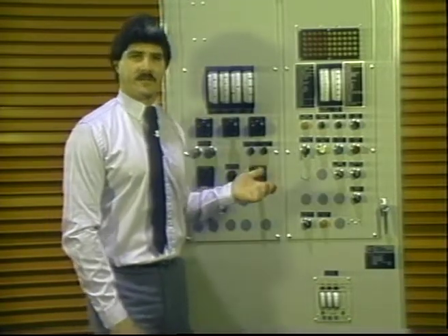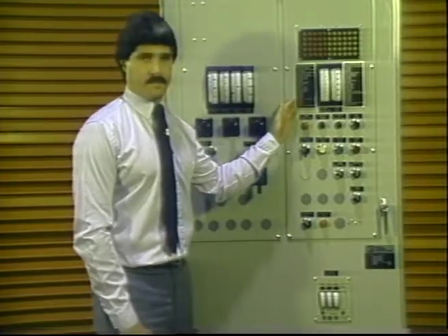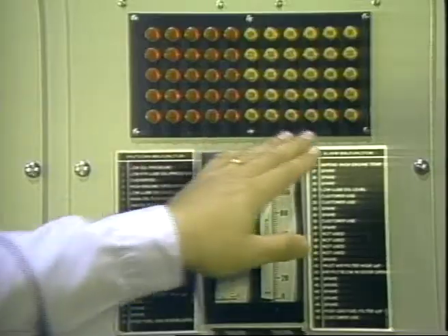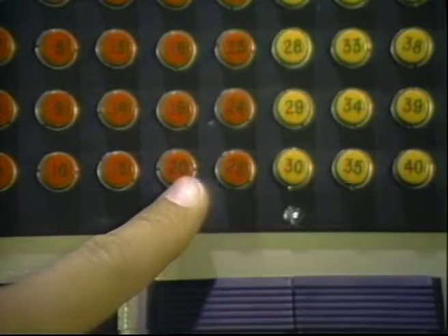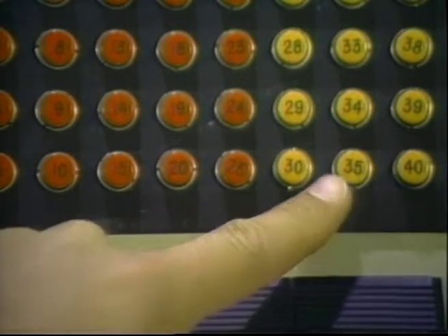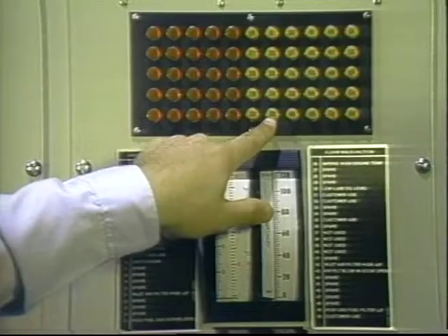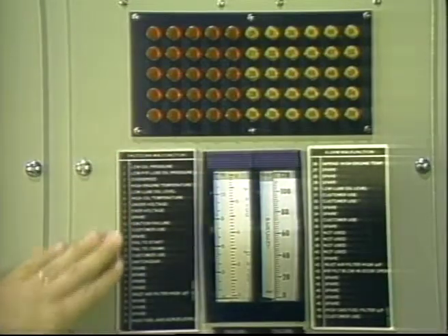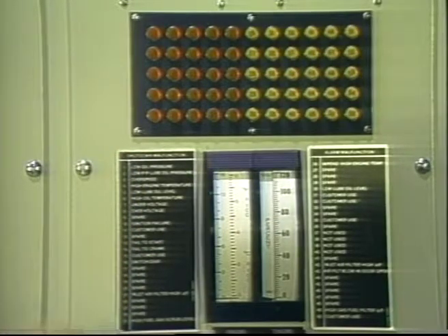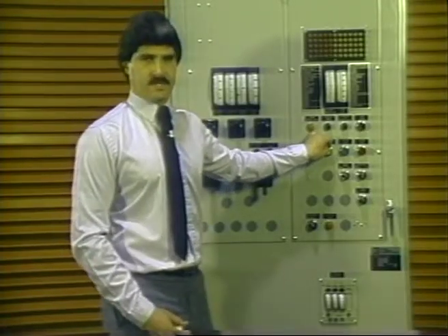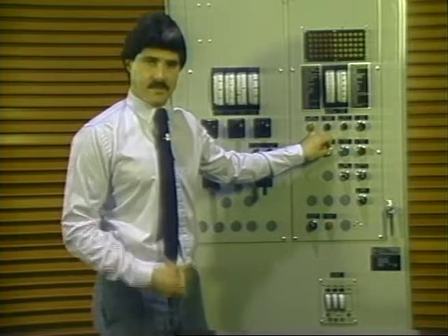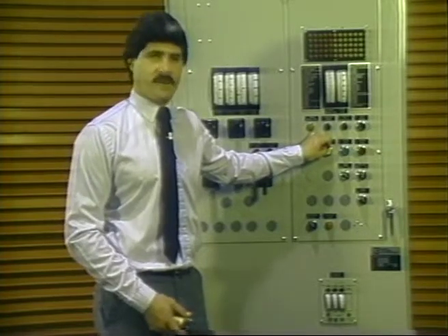Let's begin here at the console with the engine panel. At the top of the panel are the malfunction indicator lights. A red light is a malfunction shutdown indication, while an amber light is an alarm indication. Lights are numerically coded to identify specific malfunction conditions. Pressing and releasing the malfunction reset switch resets these vital malfunction summary circuits and checks to see whether any bulbs are burnt out.